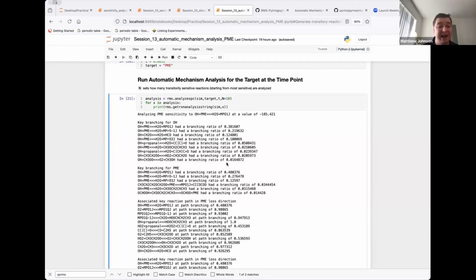In a flow reactor, the simpler case, suppose you have a gas phase flow reactor at constant temperature and constant pressure. Nominally you're simulating your reactor in space. So you measure at, say, 10 centimeters down the tube, where your detector is.